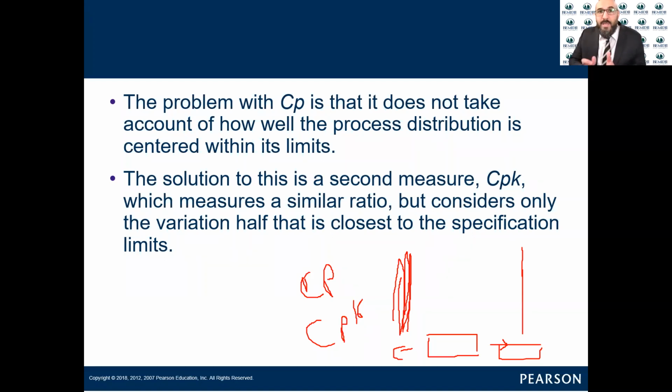Again, one calculation is to see the width of the process, whether we can potentially meet the customer needs, and the other one is whether the process is centered or not. So we need to make sure that the process is centered, so it would easily fit into the specification limits. One is the capability, the potential, and the other one is whether it is centered or not.